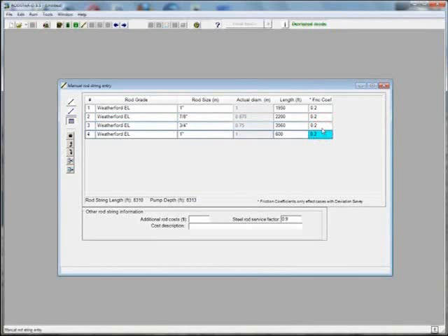You can find out from the rod guide manufacturers how much the friction is going to go up by, and then adjust these numbers accordingly. For example, if the rod guide manufacturer tells you that these rod guides will cause 20% more friction than normal, than steel on steel friction, then you multiply 0.2 times 1.2 and you use the resulting number.